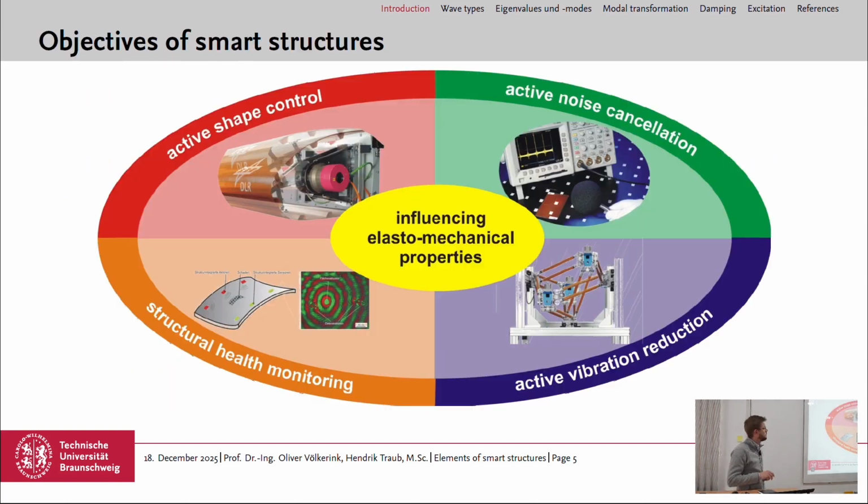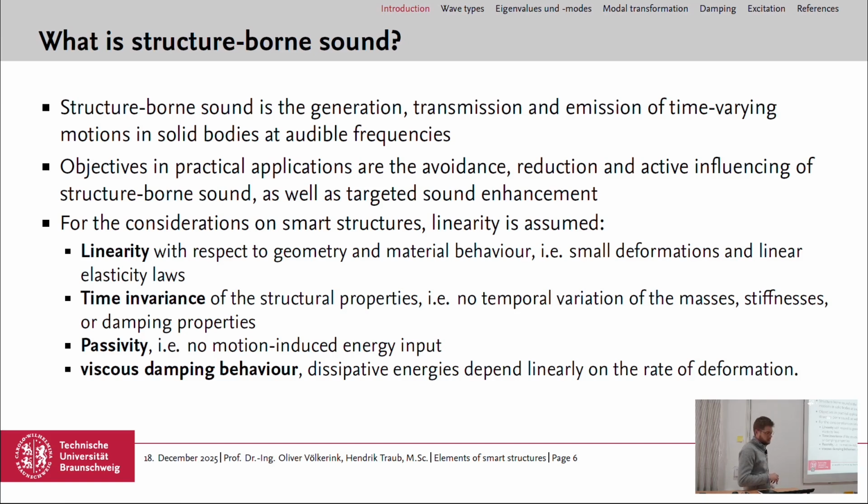Why do we have a look at vibrations? I already mentioned active vibration control, but also structural health monitoring and active noise cancellation. We need to have a look at the dynamic behavior. What is structure-borne sound? Structure-borne sound is the generation, transmission, and emission of time-varying motions in solid bodies at audible frequencies. And in practical applications, we want to avoid them, or reduce and at least actively influence the structure-borne sound.